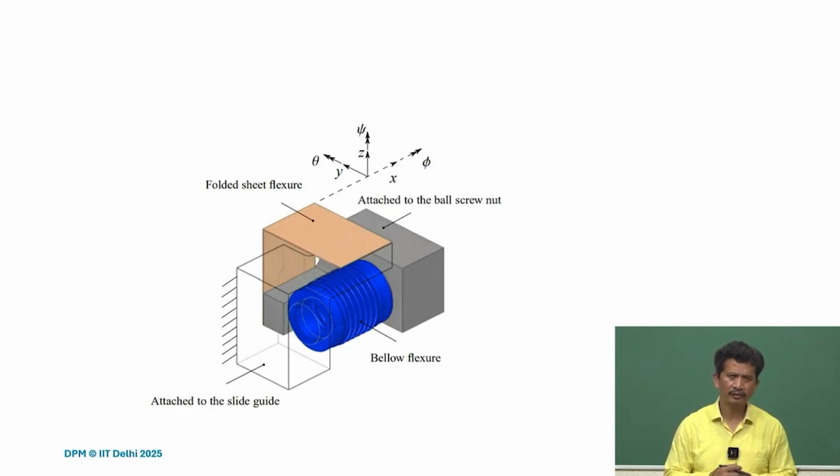For instance, we have two stages, and one is a ball screw, so we thought to use the ball screw to give the linear motion. The motor will rotate, and because of the pitch in the screw, if the nut's rotation is constrained, then it will translate. So we use that for one axis, but at the same time the rotation module is moving on a linear guide.